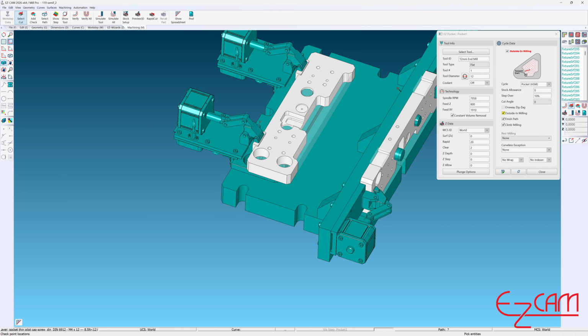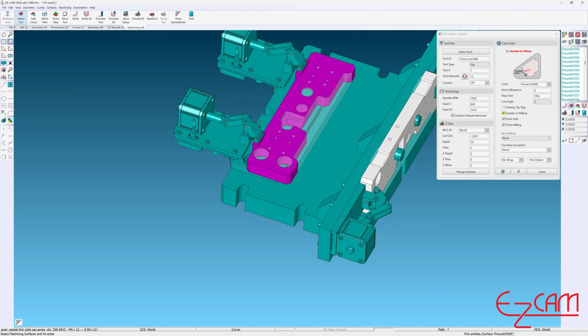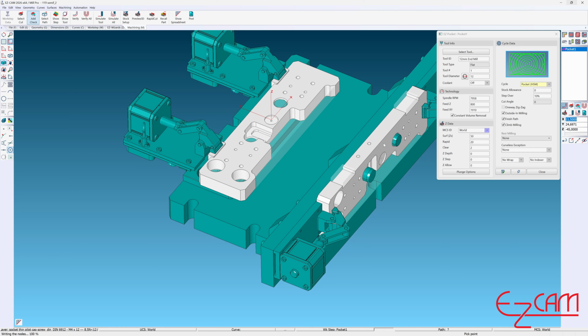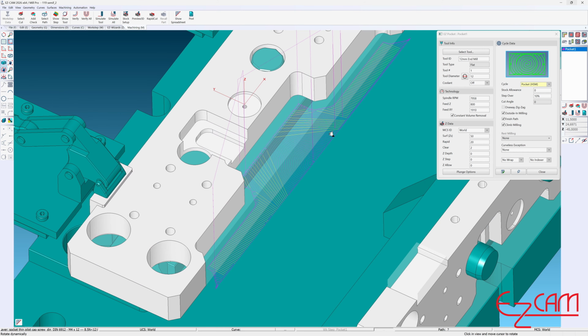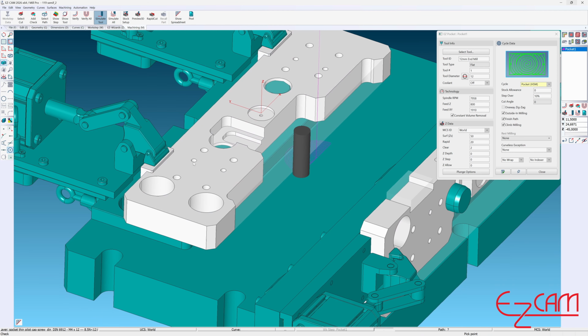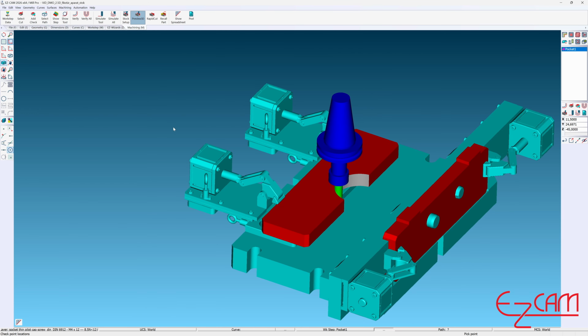Machining surfaces in this step allow the user to partially select the regions to be machined on the part by using Smart Click. In my current example, the entire model needs to be selected, so I hold down the left mouse button and frame the whole model. Then on the right side, I can define to the program that I want the area between the stock and the part to be machined. For this, after clicking the Control Surface command and selecting the stock, we can check the result with Calculate Toolpath. In this example, I don't need to include my fixtures as check surfaces because I am already working at a sufficiently safe distance. However, in another example, we will also demonstrate how fixtures can be included in the process.